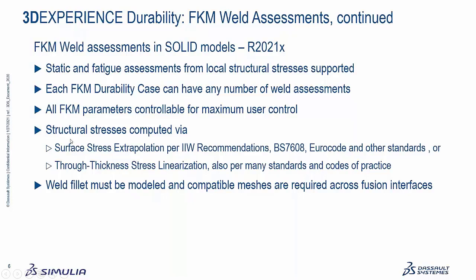What that means is the structural stresses are computed either by using surface stress extrapolation per the IIW recommendations. These are the same kind of techniques used in FKM and the British standard and various Euro codes and also in other standards.